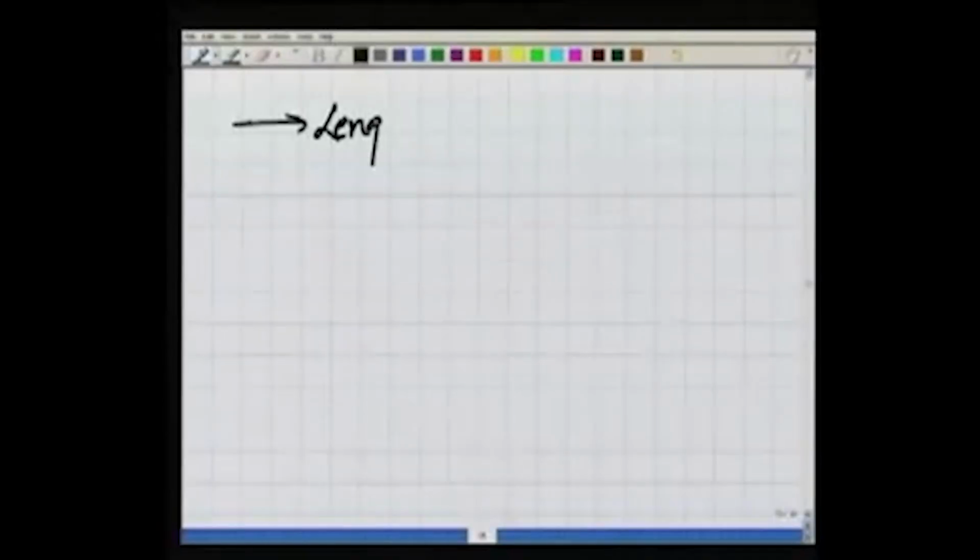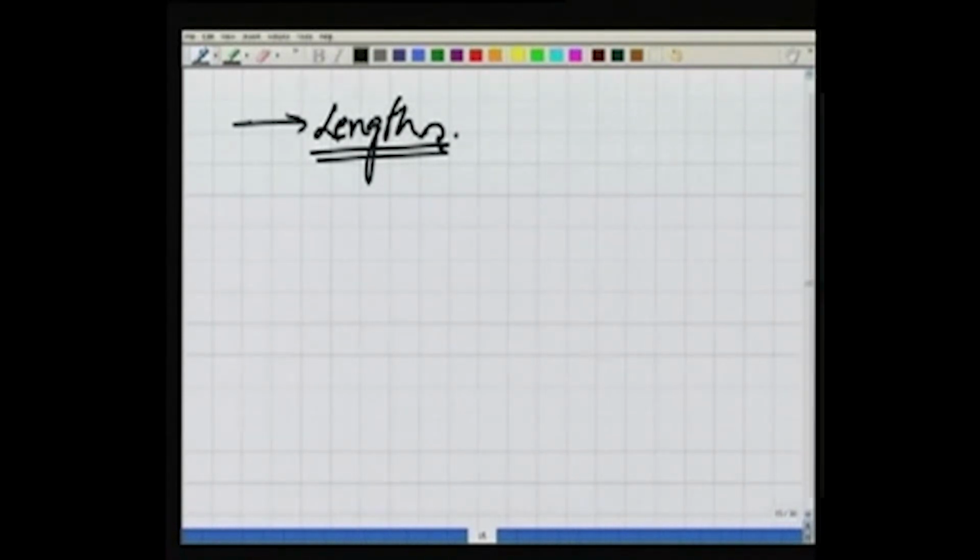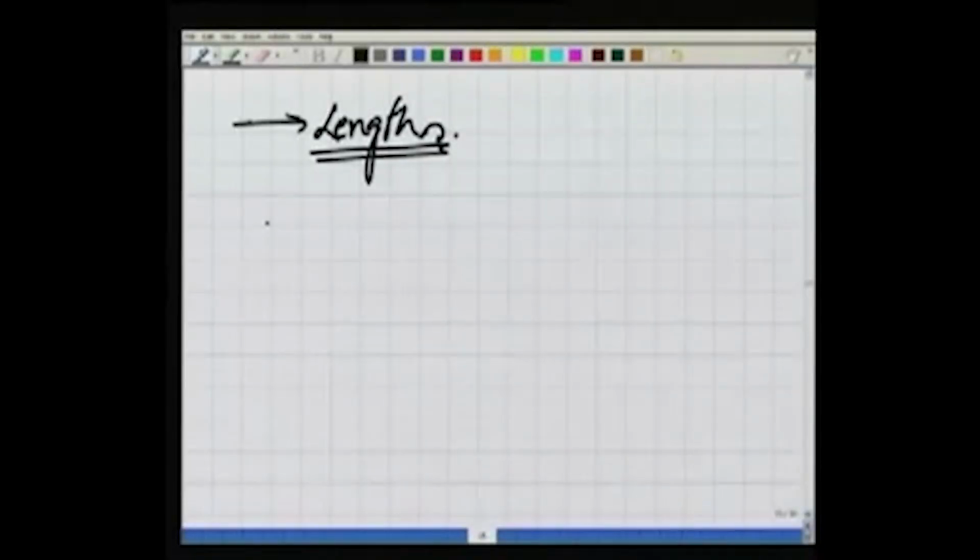So whatever figure we have chosen, the next step will be, of course, measuring the lengths or distances. We are measuring the sloping distances and the vertical angles, and we are reducing these sloping distances to their horizontal equivalent or horizontal component. So this is actually the field work.